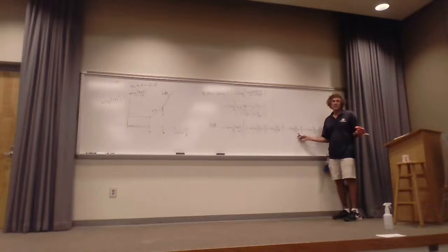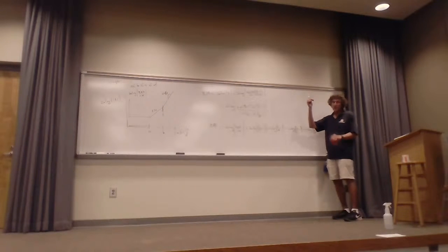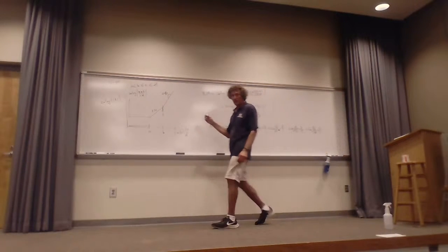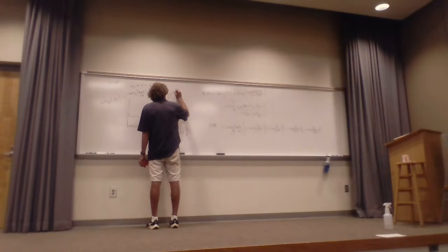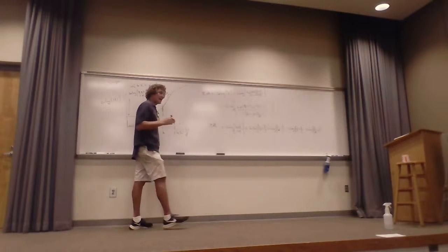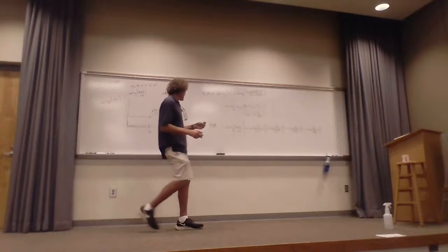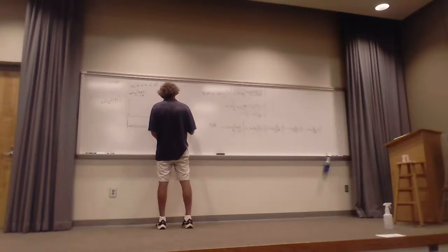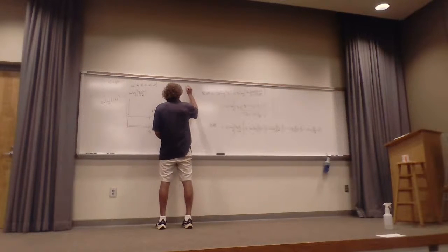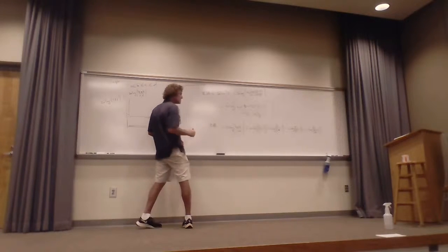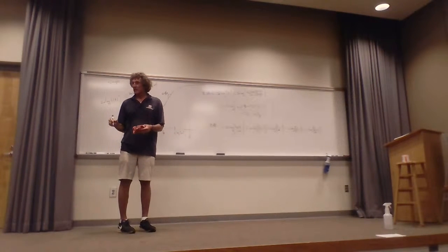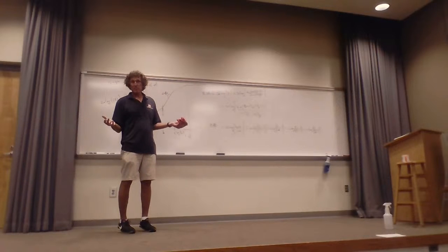Now you keep going, and I hit C. I mean, the magnitude of omega is C. With me? This one turns on. Now it subtracts 20 dB per decade from the 40, or it goes back down 20. Okay? And it's doing that, right? Then the final part, when it hits D, and this isn't exactly drawn to scale, but if that is D here, then it just flattens out. That's it. And that's how you plot all these things with Bode plots, no matter what.